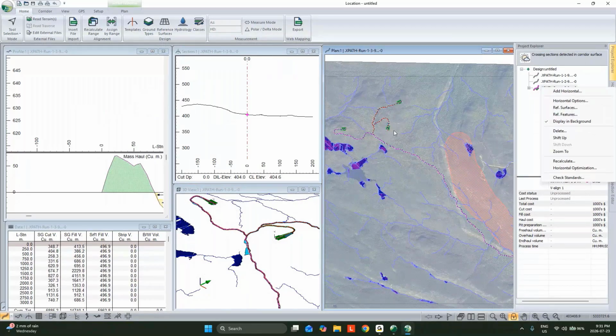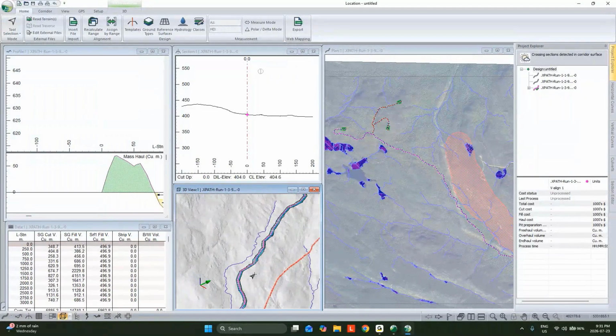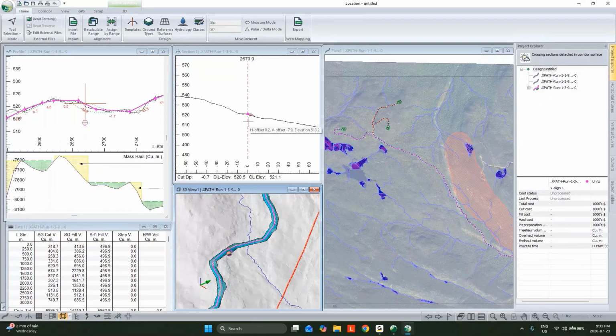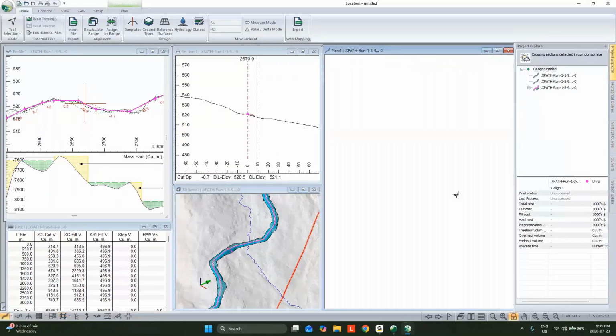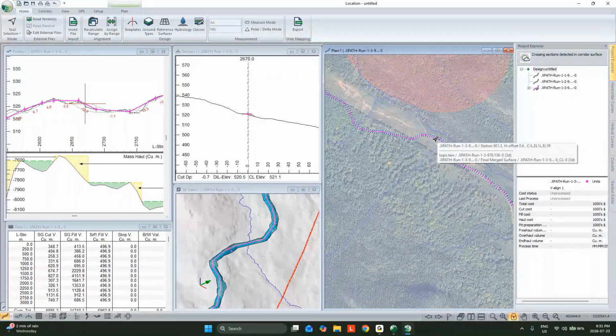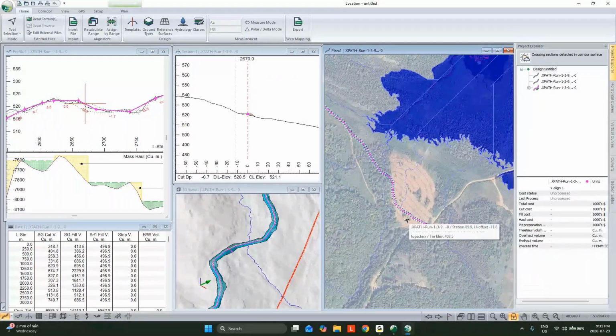Then we can take all the solution that we're looking at here, and we're going to further refine it. So right off the bat, if we just zoom in here, we will see that we have an actual 3D model appearing now for where our road's going to be. But we may also notice that there's some things that we'd probably like to refine. So that really smart line on the map that Path Explorer produces, it is a polyline. So it is considering our curvature, but it's producing a line that is a series of chords.